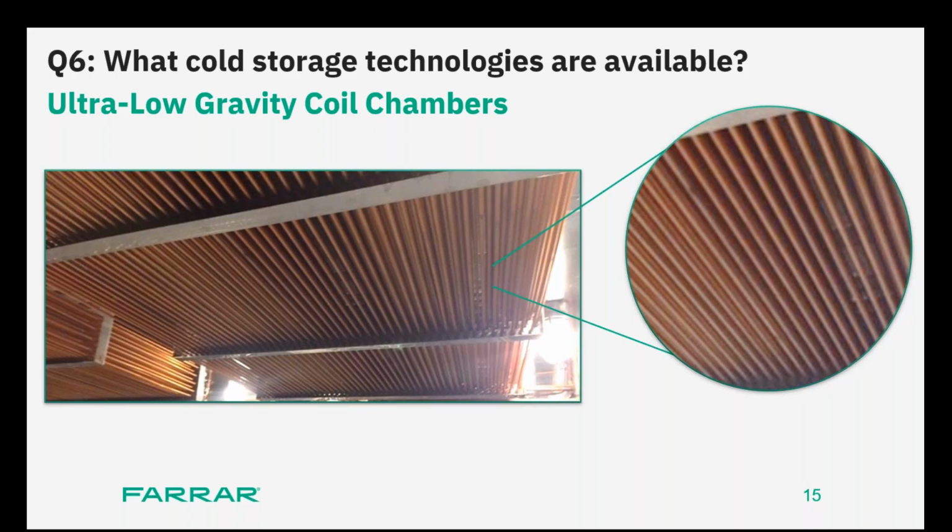And so you're saying to yourself, why did I go through so many boxes within a box, or chamber within a chamber to get to my solution? Well, it's partly because since it's a gravity coil and it's open, you have to protect that coil from getting any type of water vapor on it, because water vapor, by way of door openings and or you and I being inside of a chamber and breathing, giving off our BTUs, will go to the coldest part of that chamber, and that coldest spot is that exact coil. So they're trying to mitigate that.